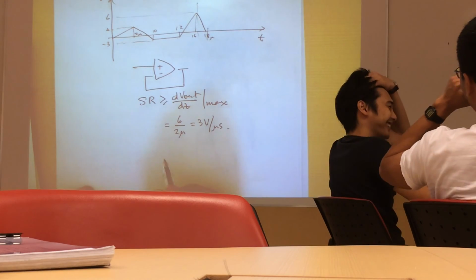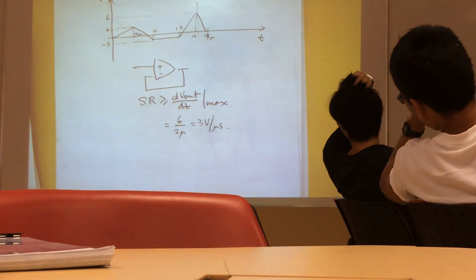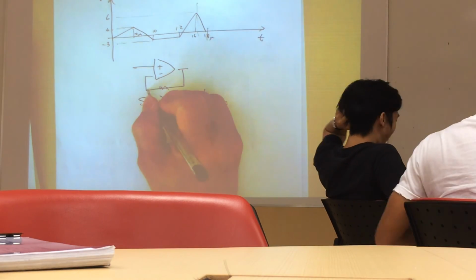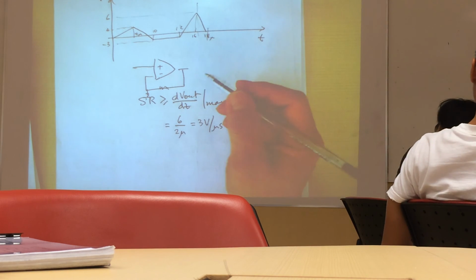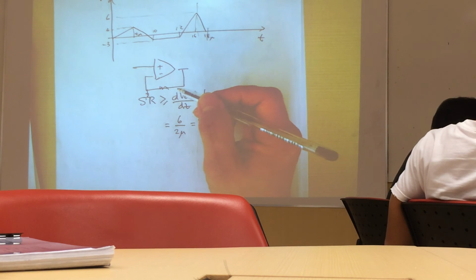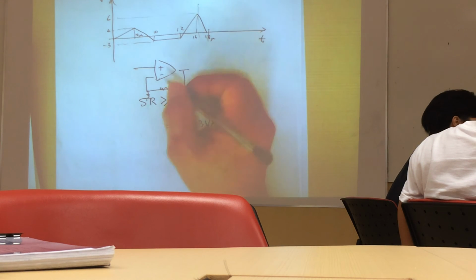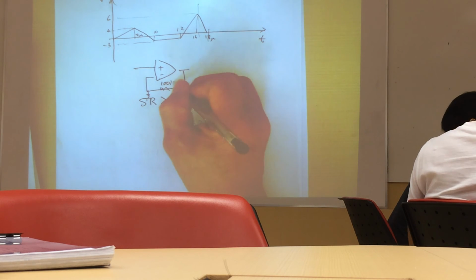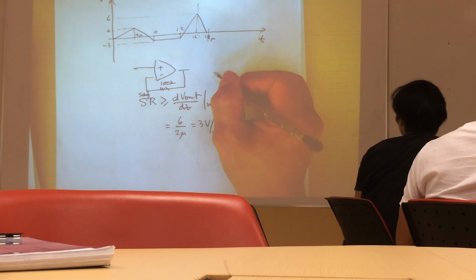Oh, okay. So now, if you now change the op-amp configuration such that we put a resistor here and another resistor here, and this becomes a non-inverting gain amplifier. And this time it says that the gain is introduced by having a 50K and a 100K. So this is a 100K and this is a 50K. And therefore this gain now is 3.